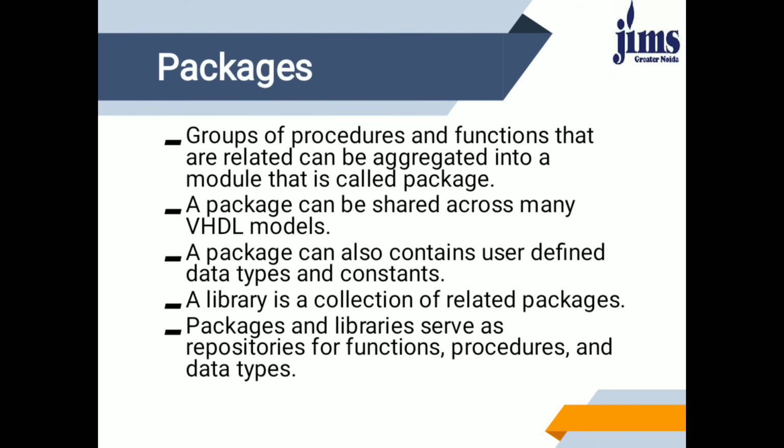As you know, generate is for repeating concurrent statements for a predefined number of times. That's why we are defining it with for generate. Or till a condition is satisfied, that means if generate. A label is compulsory to be used with the generate statements, and both forms of generate can be nested to any level.